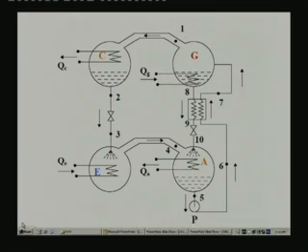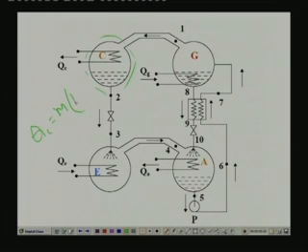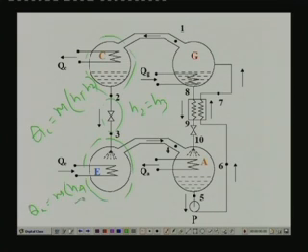Similarly, let me explain energy balance across the condenser and all, so you need not come here again. So, from energy balance across the condenser you find that QC is equal to M into H1 minus H2, and energy balance across the expansion device is nothing but H2 is equal to H3, and across the evaporator we have already shown QE is equal to M into H4 minus H3.